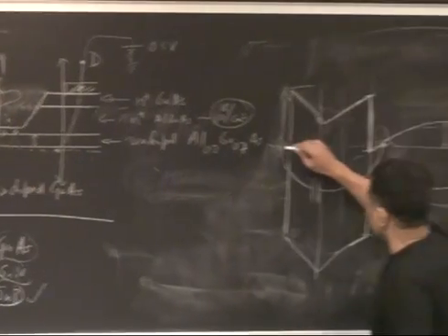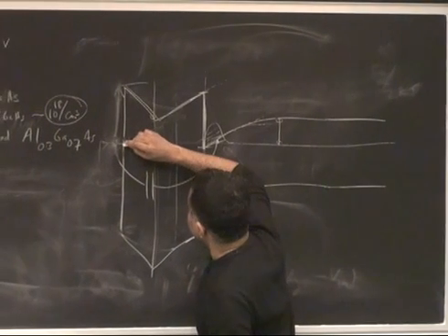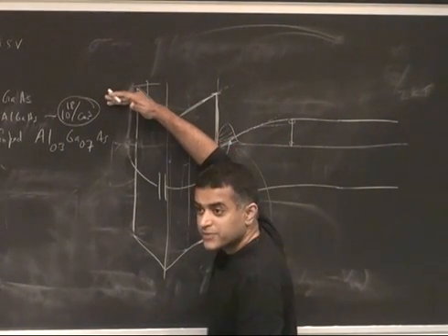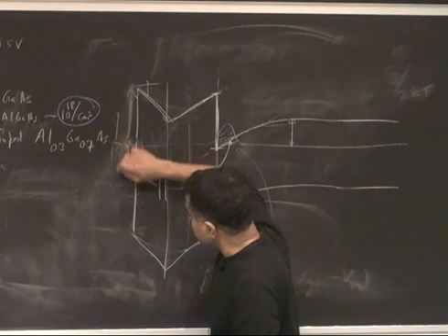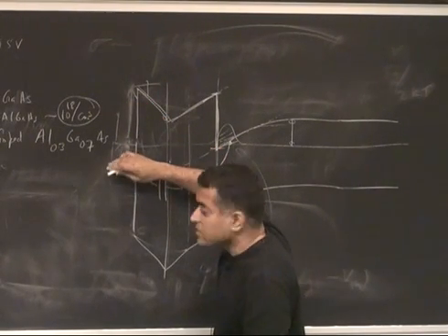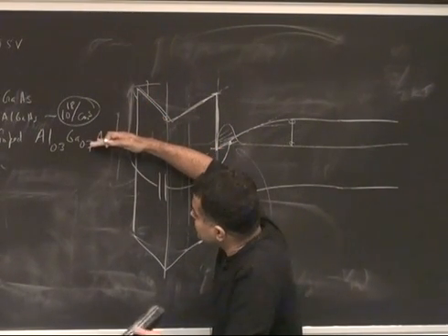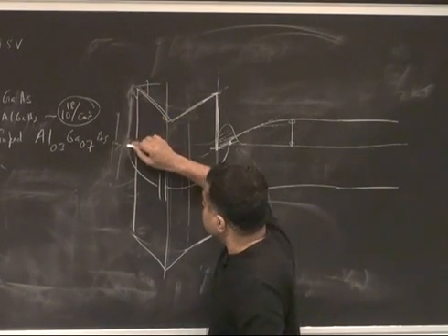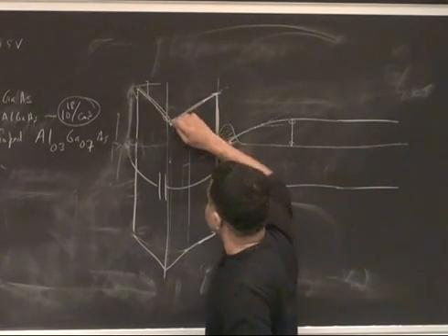In the band diagram, when you apply negative voltage, you pull the metal Fermi level up. Negative is always up, positive is always down. You can think of it in terms of the density of states: negative voltage means you're putting more electrons, so the Fermi level is going up. That's the way to look at it. So when you pull it up, all this stuff is locked.